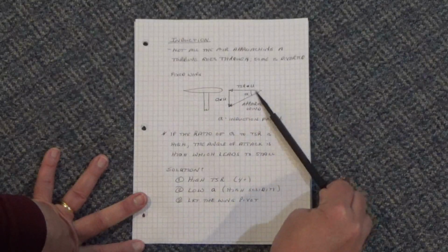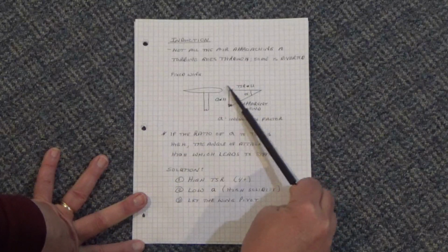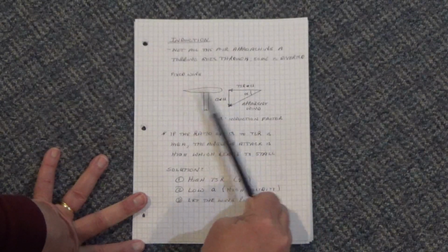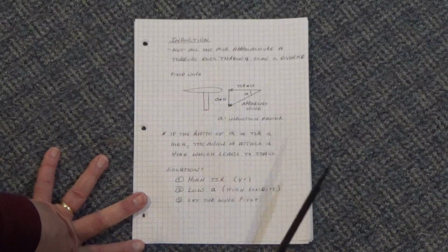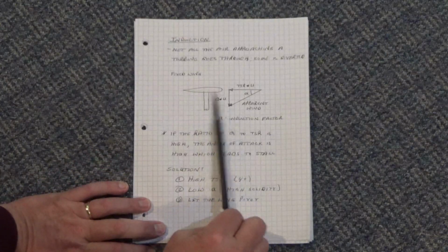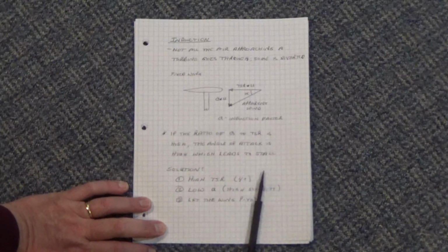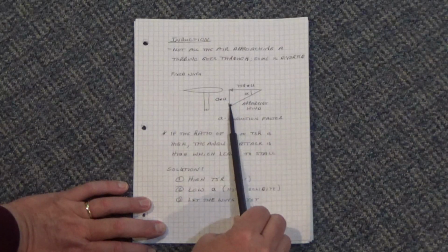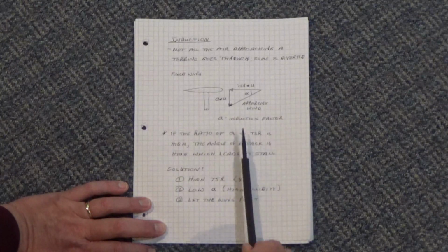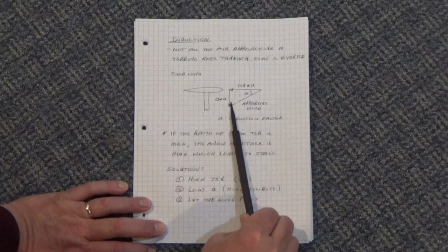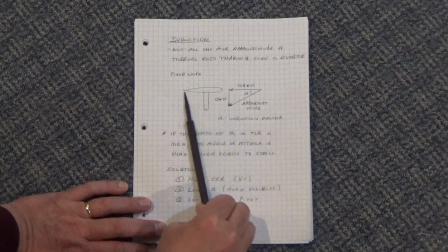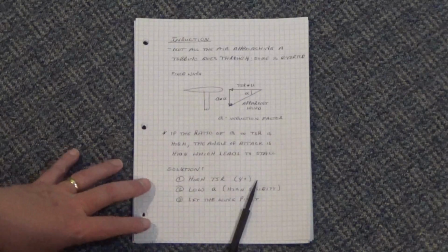You have a high angle of attack, and so if it hits this wing at a high angle of attack, you're going to get stall, and this wing is going to lose its lift and its efficiency because it has a lot of drag. Inversely, if this ratio is small, you'd have a small angle of attack, and then the air can stay attached to the wing.